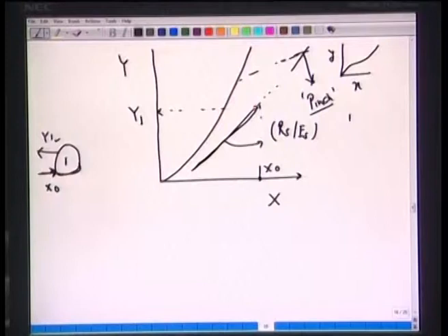In case of co-current, if you recall, we had the equilibrium curve like this, and we had the operating curve with the negative slope, which hits here, it reaches the equilibrium, where we can say that two phases are in equilibrium. Here, notice the difference: we have this operating curve which has a positive slope, and still it's possible that in some cases this line may hit the equilibrium curve depending upon what type of system we have chosen, and wherever it happens we will have the pinch, zero driving force, and we might require an infinitely large number of stages here.